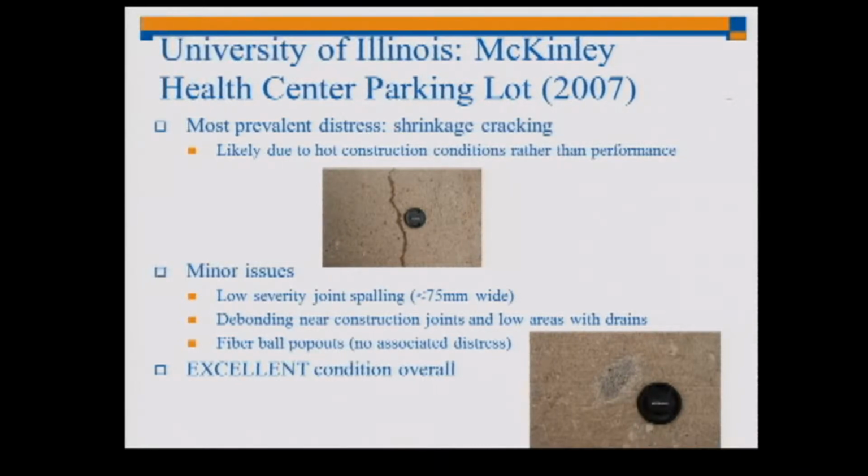Now, I wouldn't want to say there's no problems ever with these. There's some issues with when you construct these. These are very thin, and you have to deal with these generally in the summer where we live is when they construct them. So you have to do some modifications for hot weather concrete. And that means just making sure you cure it properly. In this case, we had some cracking once on one of the projects because of the wind and the hot temperature. So we just had to adjust our process of the construction.